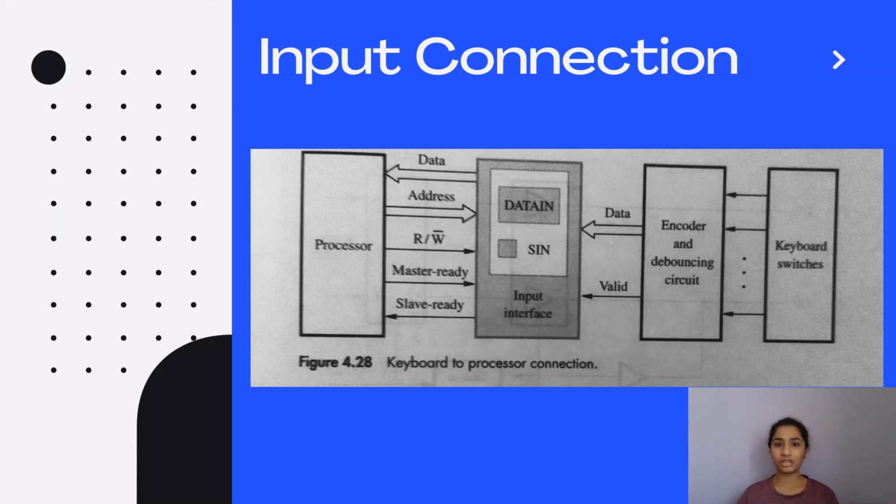In this presentation, we will be more interested in what is present inside the status flag, because it is there that we will make use of our master-slave D flip-flop. Now what is the work of the status flag? The status flag is turned to 1 whenever information is stored in DATA IN.